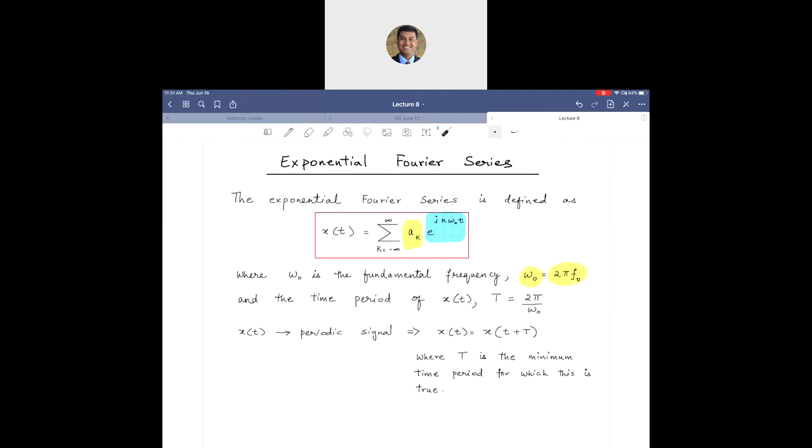All right. So our goal, what is left here? If we want to express any periodic signal x of t as a summation of complex exponentials, which goes back to the same motivation here. If you know how to decompose an input as a summation of complex exponentials, then we already know the output of those signals, because those outputs are those exact same exponentials with a change in the amplitude. The eigenvalues change, that's it. Eigenfunctions don't.